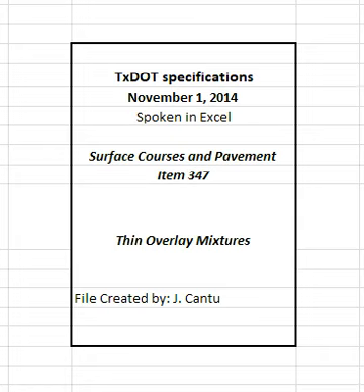4.9.2.2.1.2 Blind sample. For one sublot per lot, the engineer will obtain and test a blind sample instead of the random sample collected by the contractor. Test either the blind or the random sample, however, referee testing, if applicable, will be based on a comparison of results from the blind sample.